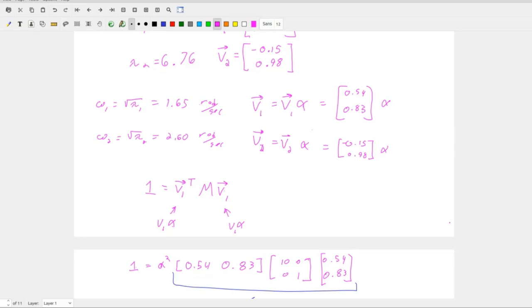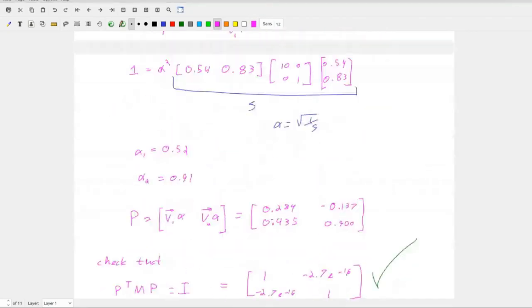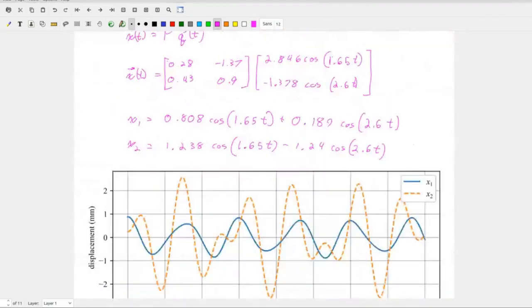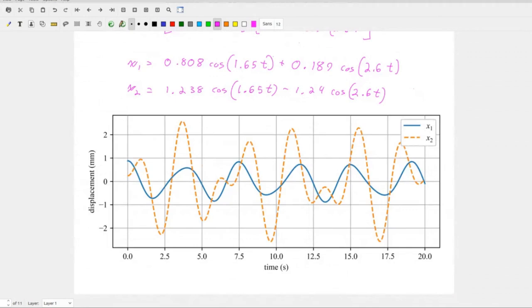So in the last example, our two masses were equal, right? Here we have a mass that's an order of magnitude larger than the other mass. So that's one of the reasons we mass normalize eigenvalues. Does that make sense? Okay. You know, the mode shapes of things like poles and cantilever beams look really pretty because it's a continuous system of mass. But other systems get real complex real quick. So here we are using both of these systems.